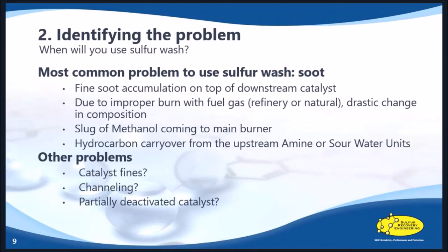Depending on the sources that you check out, some people say, okay, well, hydrocarbon carryover is not common because upstream units usually operate well. Usually it's more the fuel gas burn or the burn that would happen within, say, a direct fire reheater. And although that's correct that the likelihood is very minimal for hydrocarbon carryover, it doesn't mean that it's impossible. The little examples that I'm using in the webinar today actually are from a client of ours who did have hydrocarbon carryover from an upstream unit. So it's important to note that it definitely is possible.